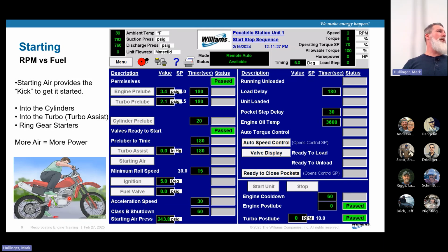What kind of air starters do you guys have in Mountain West? We have one, yes. All right. And then there's another way where they just spray air into the power cylinder. So you're spraying air into the power cylinder and it just starts going up and down just by spraying air, and spark and fuel haven't even been introduced yet. You're just moving it back and forth, okay? That's the equivalent of push starting an old car, right? Until you can finally get it going, okay? So that's what we're doing.